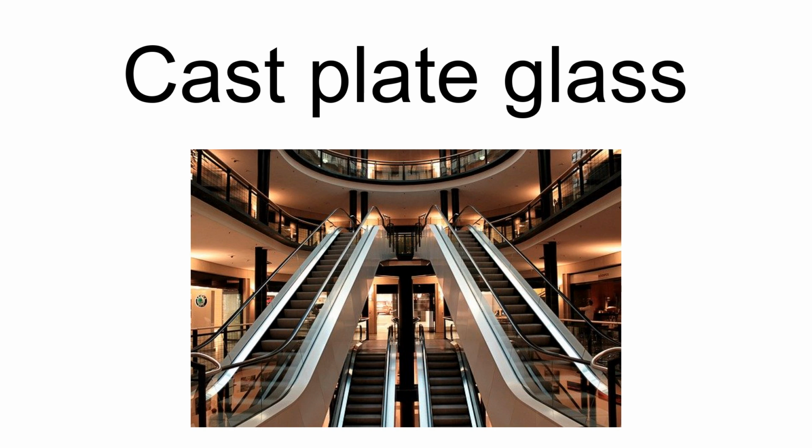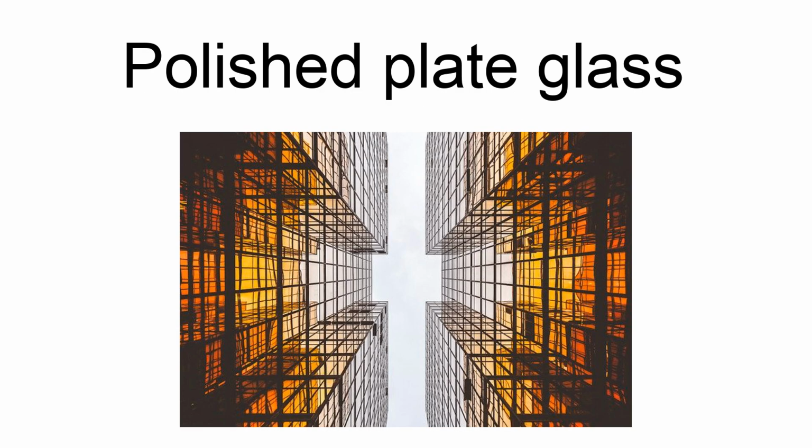Rolled plate glass was developed by James Hartley in 1848. The glass is taken from the furnace in large iron ladles, which are carried upon slings running on overhead rails. From the ladle, the glass is thrown upon the cast iron bed of a rolling table and is rolled into sheet by an iron roller, the process being similar to that employed in making plate glass, but on a smaller scale. The sheet thus rolled is roughly trimmed while hot and soft, so as to remove those portions of glass which have been spoiled by immediate contact with the ladle, and the sheet, still soft, is pushed into the open mouth of an annealing tunnel or temperature-controlled oven called a lehr, down which it is carried by a system of rollers.